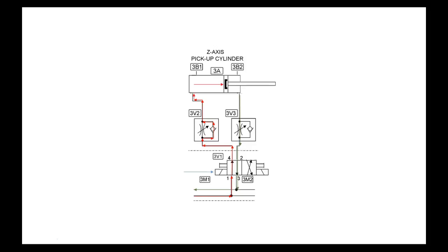None, because you have a straight piece of wire. So I can go this way and have no resistance, or I could go this way and have 100 ohms. There's 0 volts dropping there, and there'll be no voltage drop across the wire. So that wire has no resistance. It won't drop a voltage, so your resistor will not even see a difference in potential.